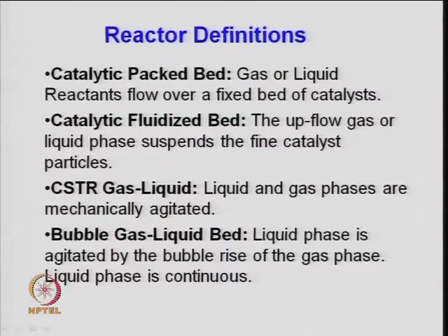For reactor definitions, as I said, the common types are a batch reactor, a CSTR, or a packed bed reactor, where you have a tubular type reactor and the catalyst is placed in the center, depending on the mass of the catalyst. We have distributors at the top depending upon the liquid and gas, and to have better distribution we need to design the distributor. So, reactor design is very complex and complicated, but in general, when you look at just the catalytic reaction, how much mass is required, that simple design can be done.